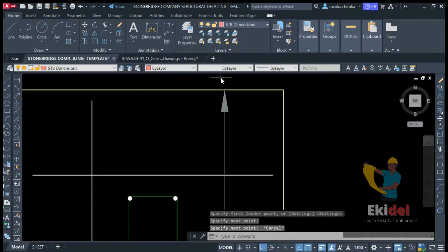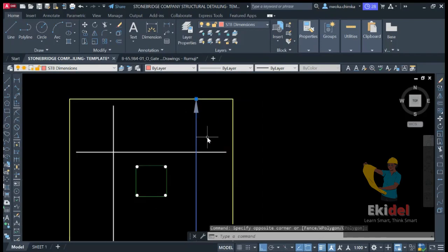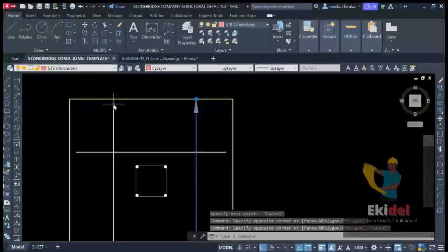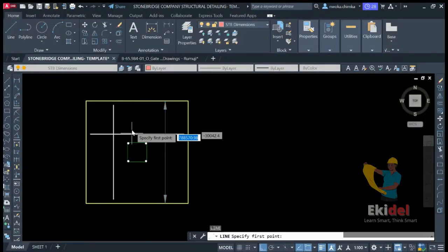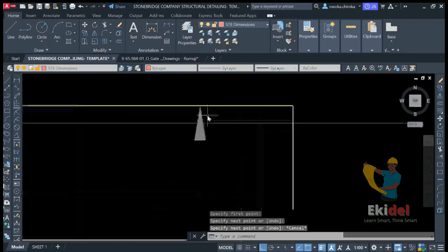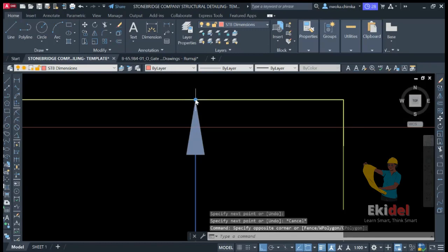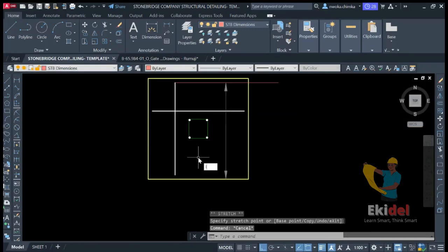Now we have to bring down our concrete cover because this direction will start from the concrete cover, because this reinforcement will span all the place from the point of our cover to the point of our cover at this point. So we already have our cover of 50 here, so just take a line outward here and then drop this point of arrow downward here and do the same thing here also.